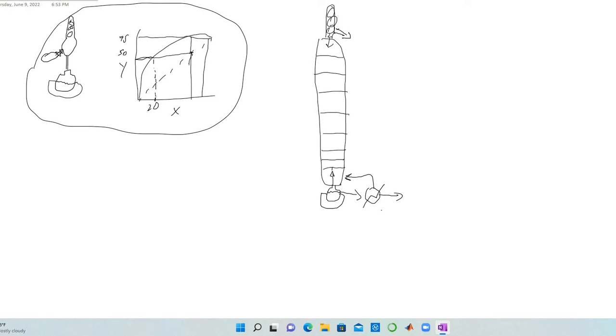As the liquid and the vapor pass by each other, I'll draw it out. So as the vapor is going up the column and as the liquid is going down the column, we're going to say we have components A and B. Alright, so we're going to have component A and component B in this column. For the sake of the argument, we're going to assume that A is the more volatile, which means A is going to boil more readily than B in this mixture. And so these X and Y's are going to be in terms of the more volatile component A. So, as we're going up, we're going to have our mixture of A and B, and as we're going down as a liquid, we're going to have our binary mixture of A and B.